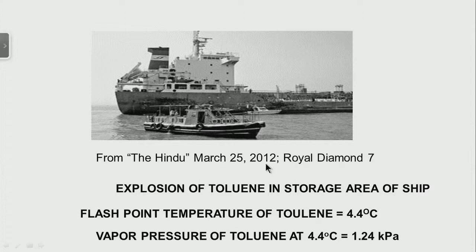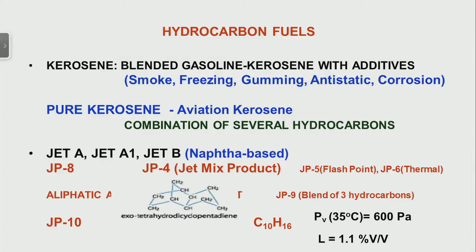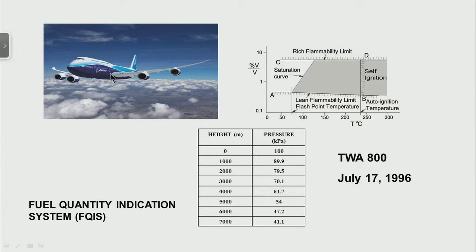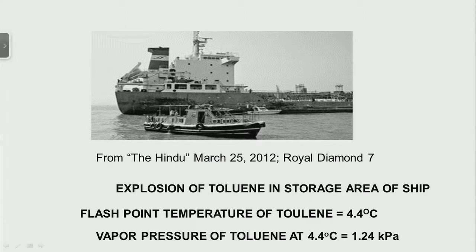You know, the month is always important because the month will tell you whether the ambient temperature is high or low. Like in the previous example of the aircraft, the Boeing 747, we noted it is summer, and the fuel tank is somewhat warmer at 35 degrees. And mind you, I forgot to mention one thing here. In the earlier example you had the refrigeration system of the aircraft, and the aircraft was slightly delayed in departure, and the people were sitting inside and the refrigeration system was working. Whenever a refrigeration system is working, hot exhaust gases are generated, and it kept the fuel tanks a little warmer, and that is also one of the criteria which went into keeping the fuel tank warm. Well, let us get back into this particular example.